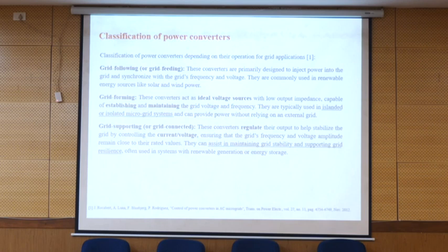But when we say grid forming converter, grid forming is not the converter, it is a conversion system. The converter can normally be just a conventional two-level converter, but it is controlled in a way to react as a voltage source. So later, if someone asks you what the grid forming converter is, you say that this is the type of conversion system which acts as a voltage source.